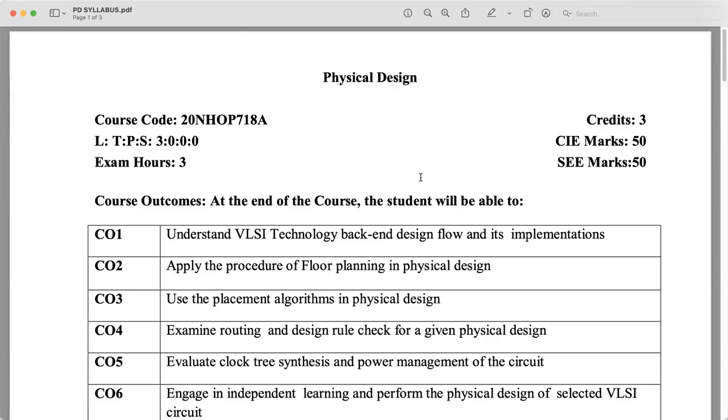So we are going to take this a little further, okay? Here in physical design, we are going to actually manufacture the chip before we get into GDS2, which is nothing but the Graphic Data System for information interchange. So before getting into that, we will actually decide how the IO pads are going to be placed, what is going to be the distance between the core and these pins, right?